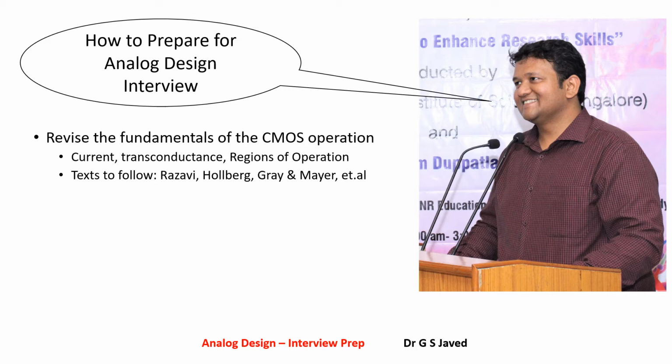Also find out what are the current, transconductance or gm, and regions of operation, linear, saturation and cutoff of all these devices. Also pay a lot of attention to how you bias a device for its required operation.